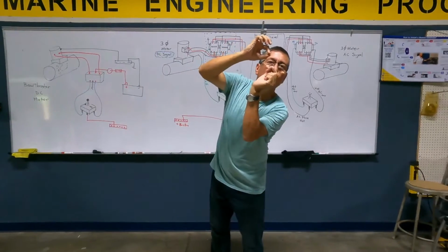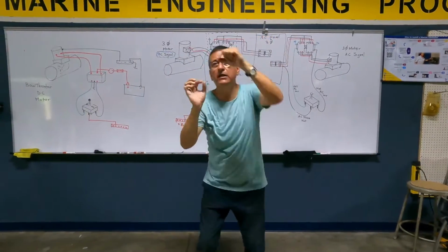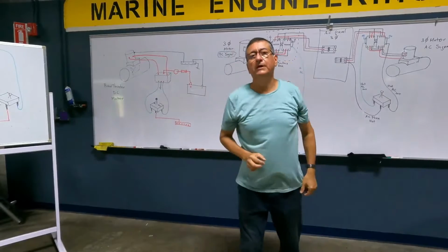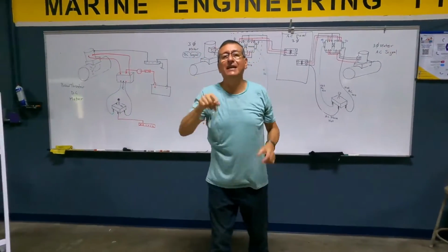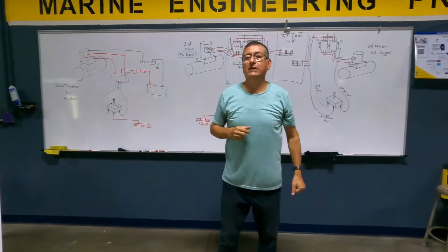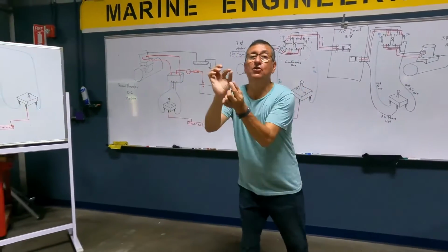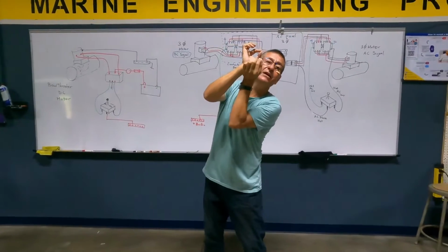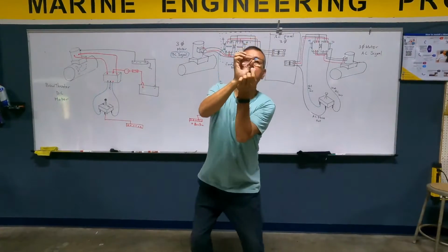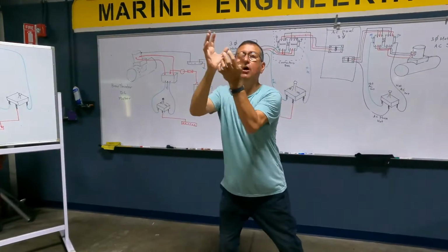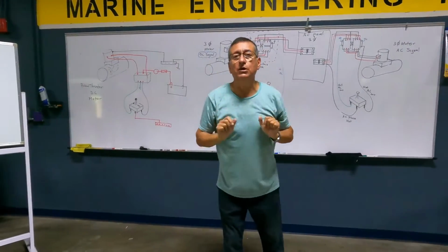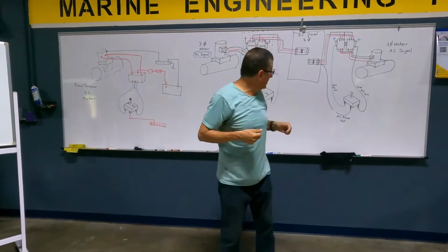In this contactor, 110. In the other contactor, 0. I don't have signal coming in the second contactor. Let me connect an extension cord with 2 cables in any outlet. Let me check contactor number 1. Okay, good. Let me check contactor number 2. Okay, good. The contactors are good. It's the signal that is not coming.